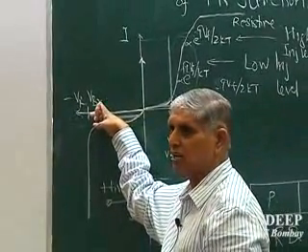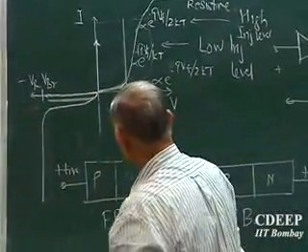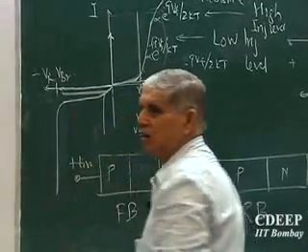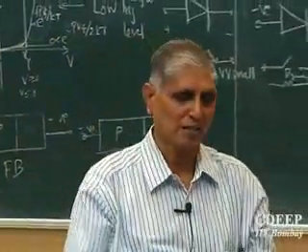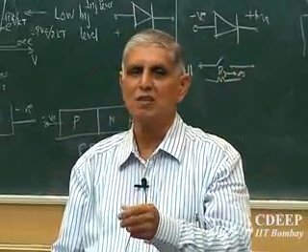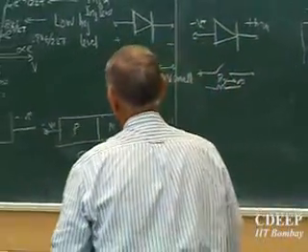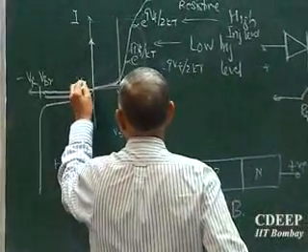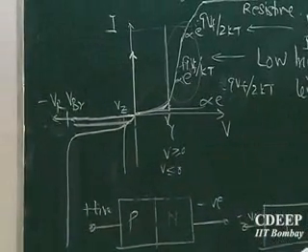So there is this fact that there is a limiting voltage in the reverse bias up to which you can work, and we want to know the phenomena. Now it has been found, and this is why I am interested to know the phenomena, that some diodes break down as low as 2 or 3 volts or 4 volts or even less than 2 volts. That means as soon as you reverse bias with a little voltage, it short circuits. This breaking down of a diode at a very low value is named the Zener voltage, VZ.